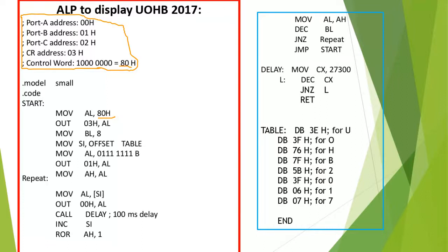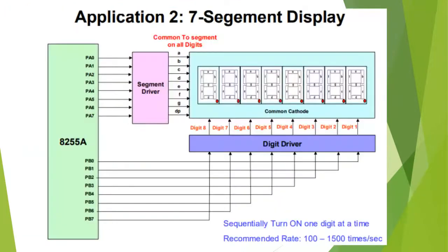Why do we actually use it? I tell you, because if you can see here, we have to turn on the LEDs one at a time. Only one LED should be on. For example, the first one is on first. This one is connected to port P7. So that means all the bits should be 0, 0, 0, 0, 0, 1. Actually, it can be done a different way.